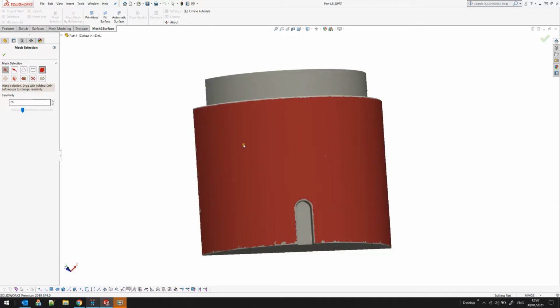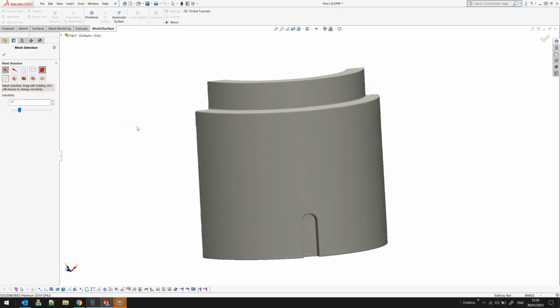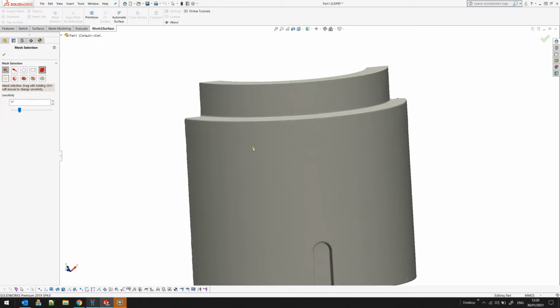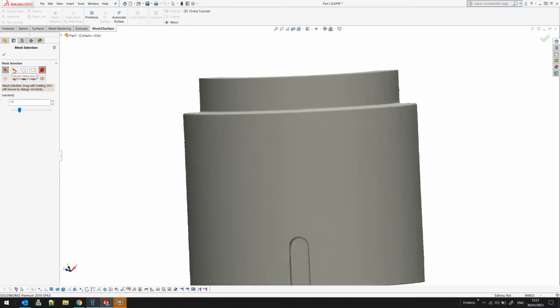To avoid moving the mouse left and back to the scene, if you hold Control and hold your left mouse button while you move, you change the sensitivity of the algorithm. So again, you need to hold Control and the left mouse button and move up and down. So this is the first way of selecting triangles. At any point when you have something selected and you want to start again, you can use the button called Deselect, which removes any selection that you have created so far.